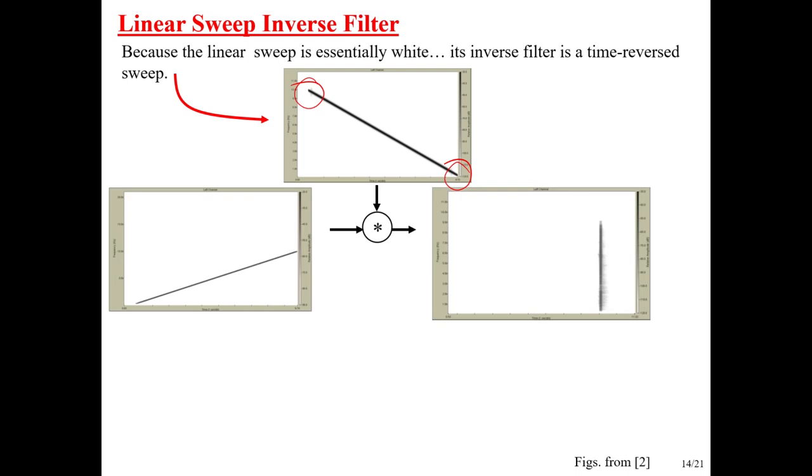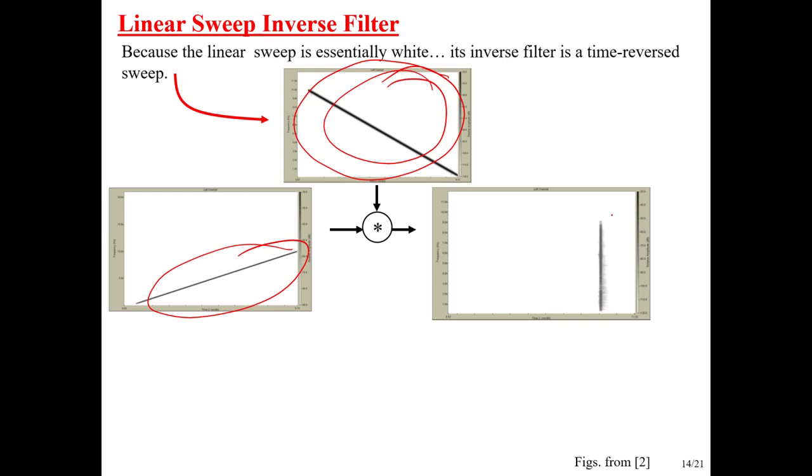But if you do analyze this, again, I don't go through all the details, we can think about this being a filter, and we can analyze it with group delays and phase delays. And what we can see is that when you do this convolution, it's basically delaying these things different amounts at different frequencies so that they all end up concentrating at the same time.